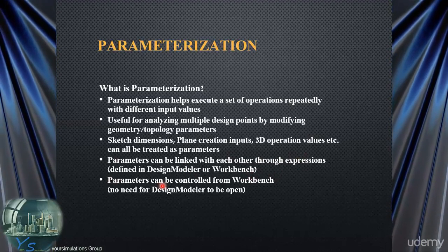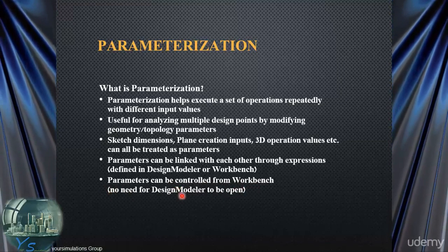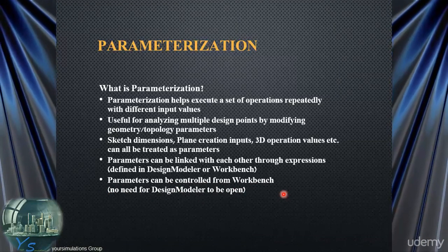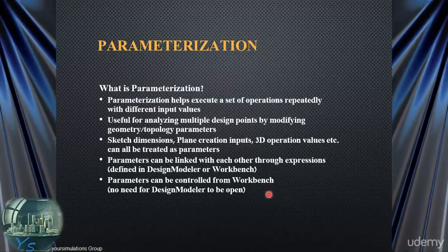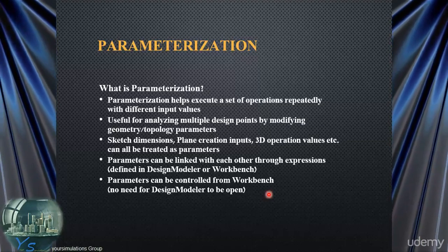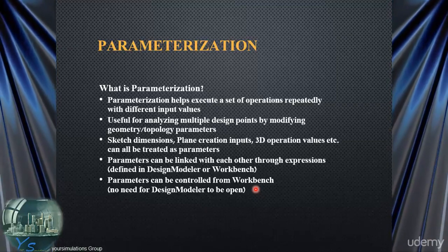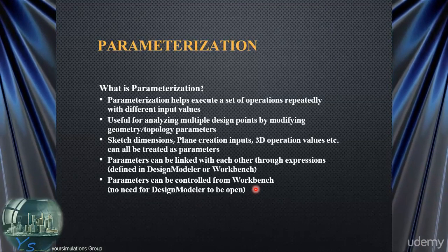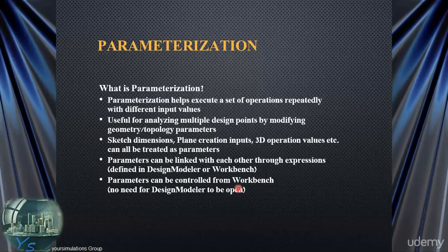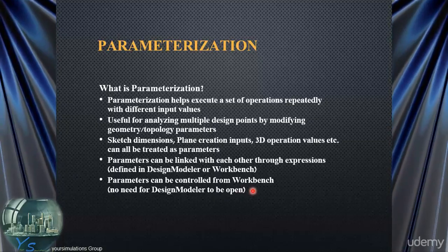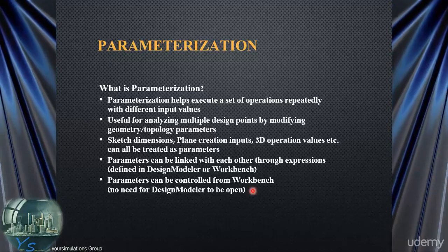And also an important point as far as Workbench is that parameters can be transferred across applications within Workbench. So that once we've set up all our parameters, whether they be geometric parameters for Workbench or solver-based parameters as far as the solver is concerned, we can then control all of the design changes from Workbench itself, and we need not go down into the individual applications once they've been already exposed in those particular applications themselves. We can then control the entire simulation at the Workbench level.